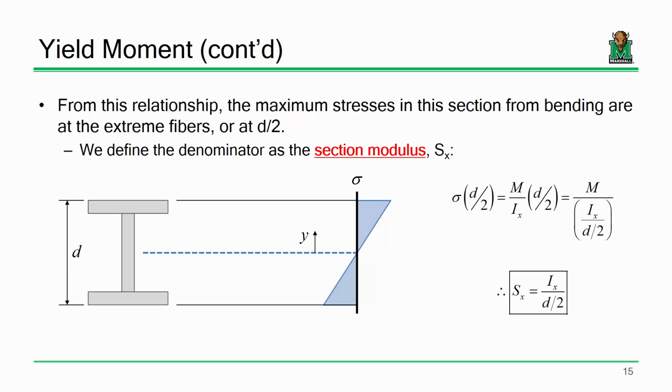Also, the idea of a section modulus. If I have a moment of inertia and I have a stress profile, I recognize the largest stresses are either going to be at the way tippy top of the section or the very, very bottom, right? So I can say, all right, let's take that moment of inertia, divide it by, remember, an extreme fiber distance from the centroid to that extreme-most fiber up top or that extreme-most fiber on the bottom, and generate a section modulus. Remember that?